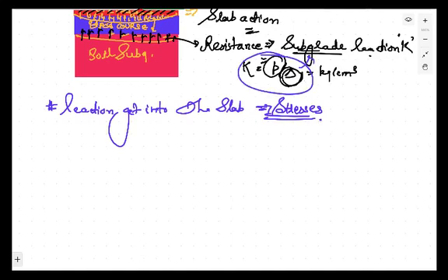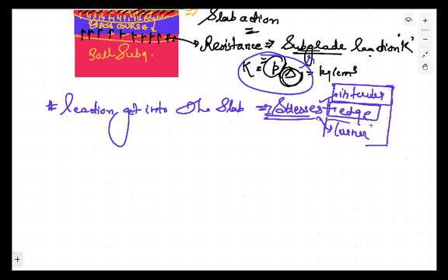Now, that resistance gets transferred into the slab in the form of stresses, and those stresses are produced at the interior, edge and corner of the slab, which can be the reason for the failure of the slab if not properly prevented. It means that what we have to do in transportation is calculate the stresses at the interior, at the edge and at the corner because of the reaction which is produced at the soil subgrade.